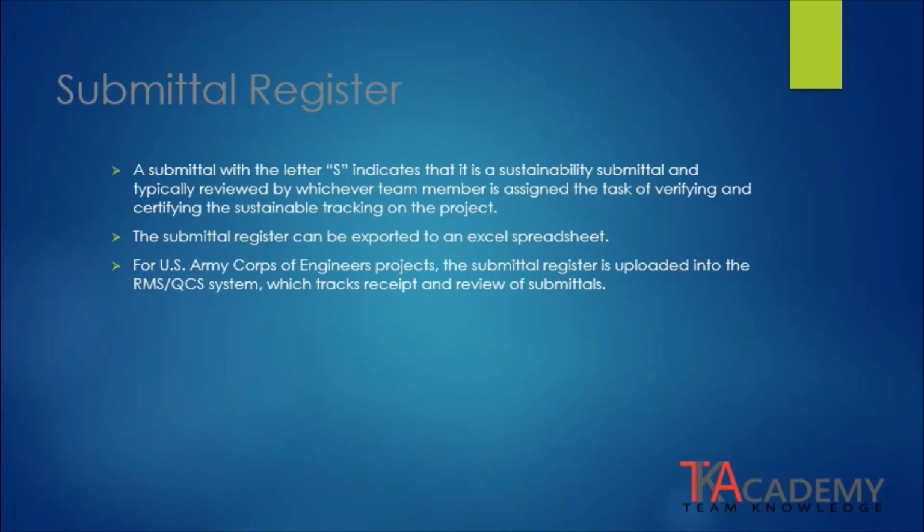A submittal on the register that has the letter S indicates that it is a sustainability submittal and is typically reviewed by whichever team member is assigned the task of verifying and certifying the sustainability tracking on a project. When the submittal register is generated at the end of the project, it can also be exported into an Excel spreadsheet. For projects involving the U.S. Army Corps of Engineers, the submittal register is uploaded into their RMS QCS system, which is used for tracking receipt and review of submittals.